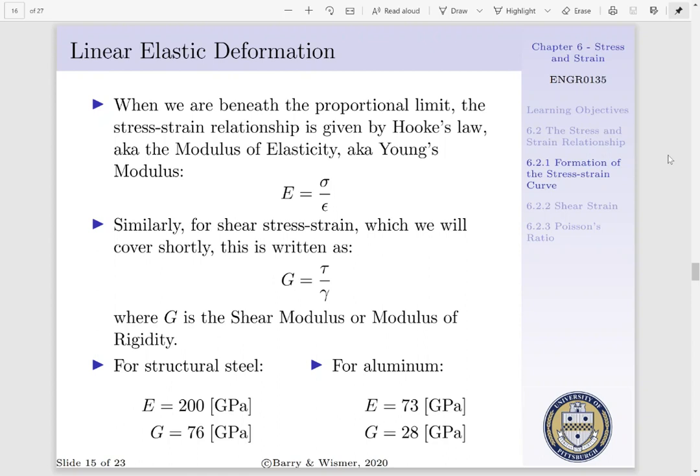Now, as noted, the modulus of elasticity quantifies the resistance of our material to deform via axial loading. A material with a high modulus of elasticity can withstand a high stress before eliciting a certain amount of deformation. Our shear modulus, or modulus of rigidity, is the resistance to shearing. A material with a high modulus of rigidity can withstand a very large shear stress before eliciting a certain amount of deformation.